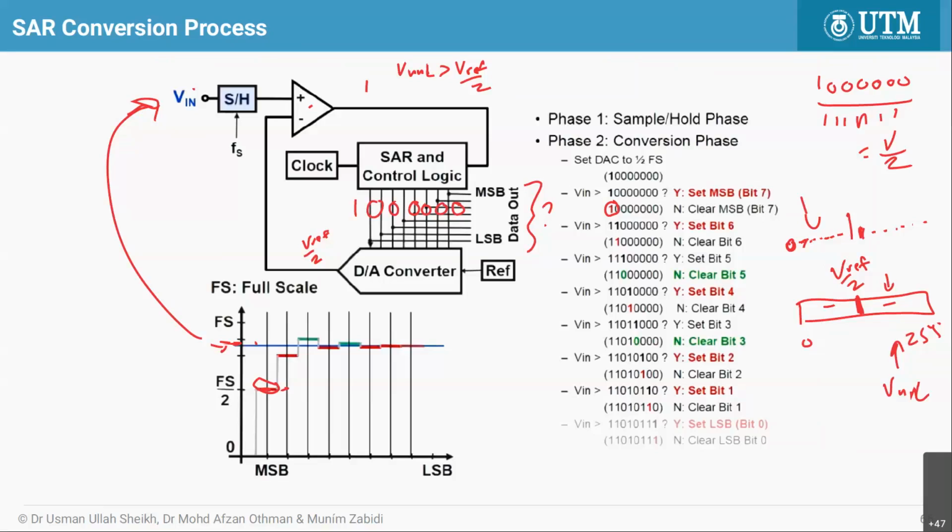Okay, good. Then after that, you zoom in again. So now you know the voltage is between Vref by 2 and Vref. But in this case, I want to know the second bit. I know the first bit is 1, but the second bit I do not know yet, and I have other bits to finish later. So now we want to know the second bit. The second bit here is going to be between Vref by 2 and Vref.